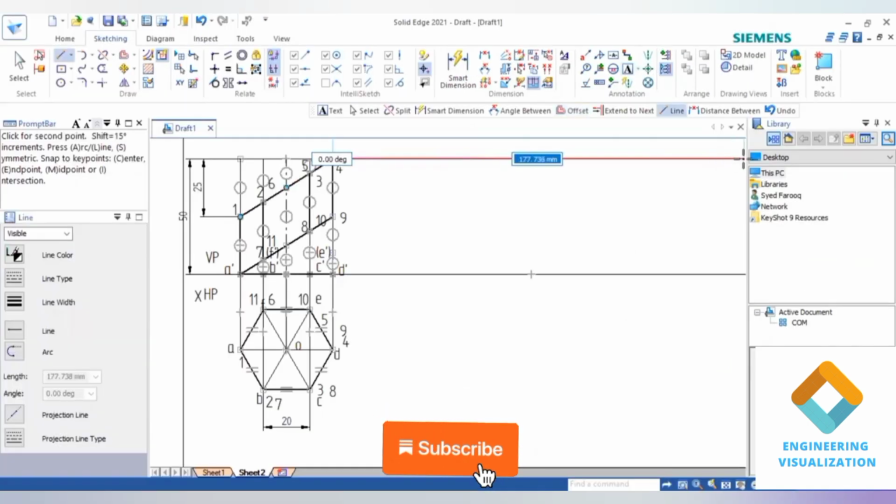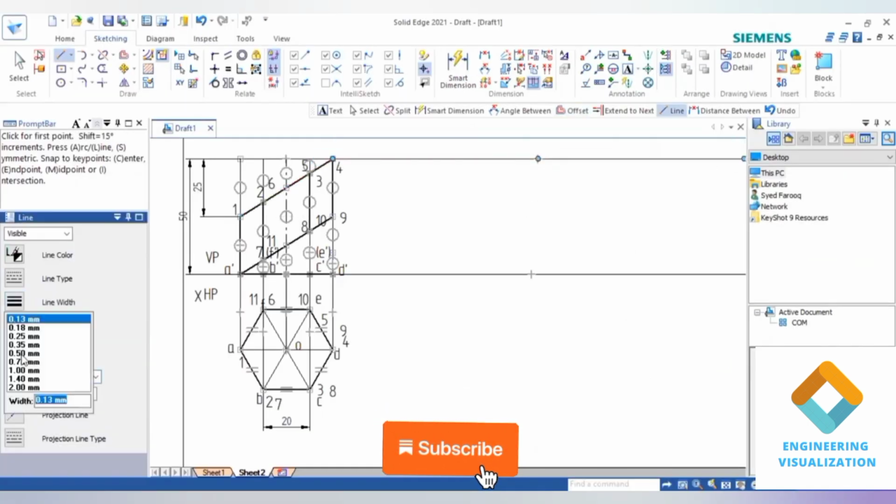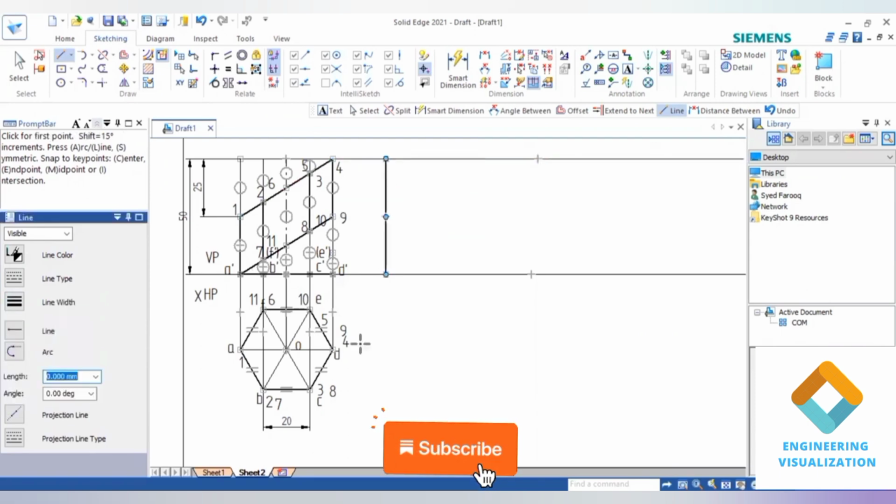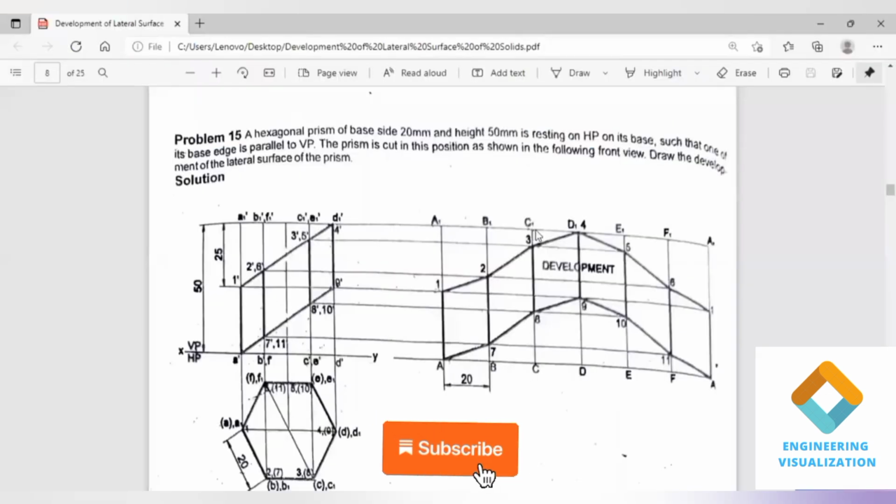First we draw a parallel line here. After that we'll draw one vertical line. Okay, vertical line we draw here. After drawing it, since it is a hexagonal prism, it has to be set using the offset command. So I'm going to construct it.